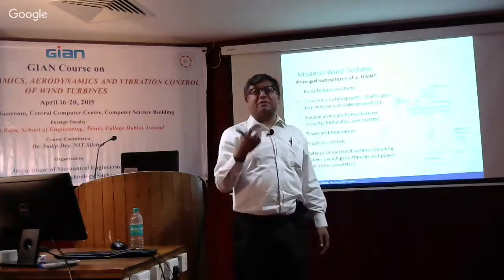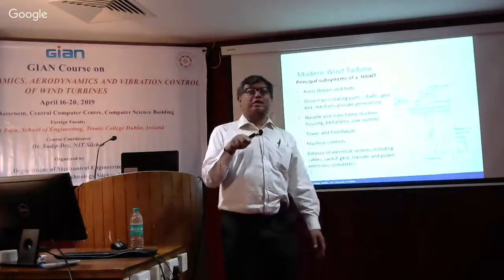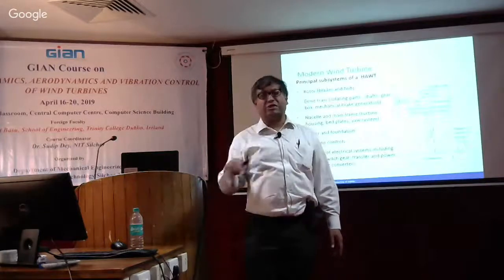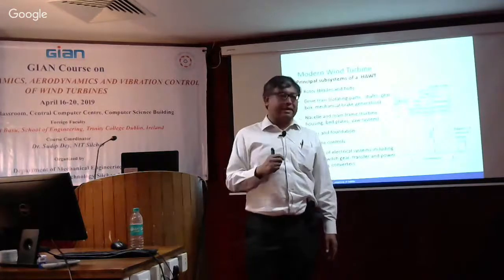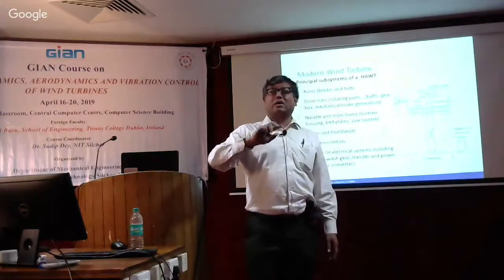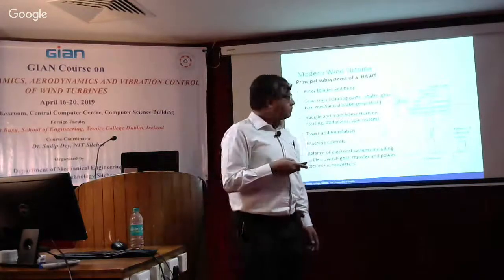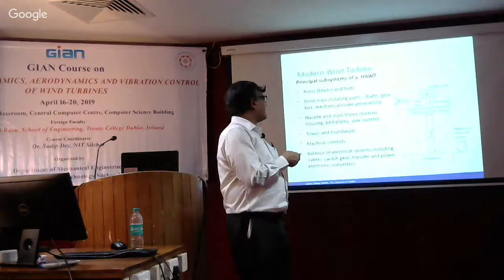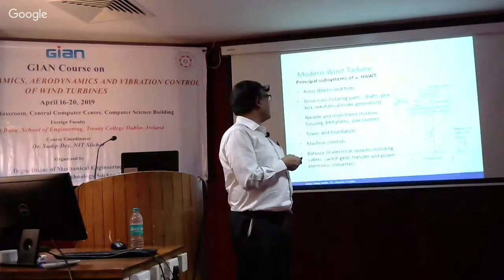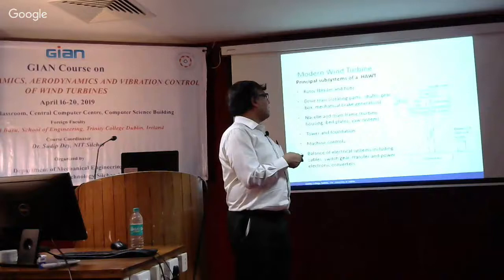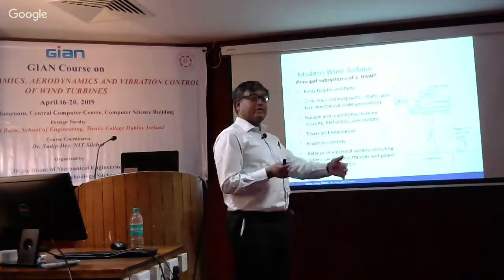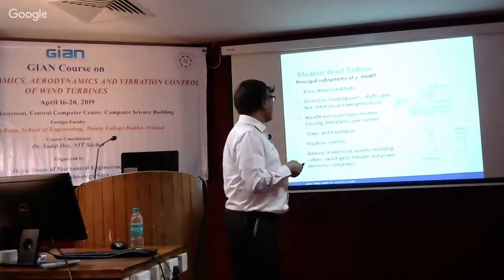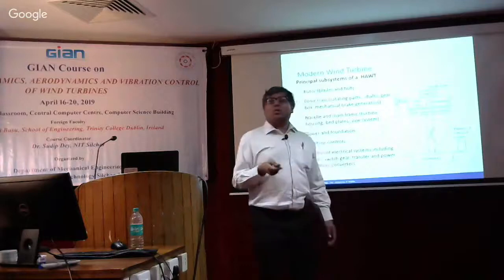So the aerodynamic load will change, but that will also change the torque. So the load is not just a load; the torque is actually generating power, because torque multiplied by your rotational speed gives you the power. So the torque is also contributing to power generation, and you need to control that as well. Therefore, there is also a pitch controller and torque controller here. And then you have a yaw controller to control the movement of the nacelle at the top, to properly angle or align it. And then you have the power electronic controller, which controls the quality of the power.